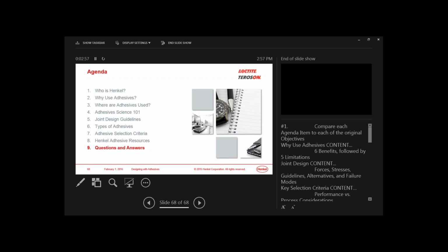Well, that's a complex need. We do have a large number of adhesives that are well suited for bonding glass and exhibit exceptionally high bond strength. However, a lot of these adhesives would be kind of a pale yellow color, unless, of course, they're in a very, very thin film, and oftentimes that pale yellow color is so faint that it really appears optically clear. We can't say that we have a true crystal clear adhesive. They always have some type of a pale yellow appearance to them.